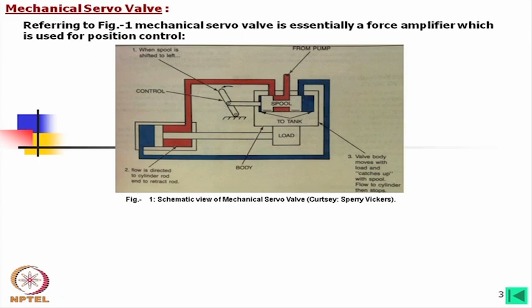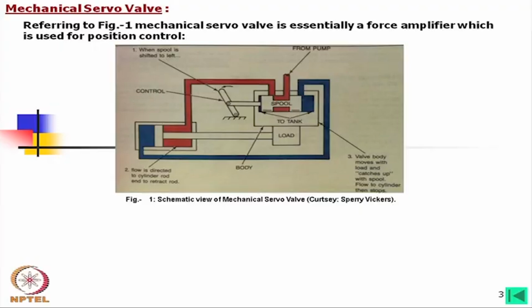For example, if you use a solenoid, a certain amount of constant input is there. So, due to this input, again this will open, again the valve will close, and this will go on. That will occur simultaneously and so smoothly that there will be no discrete motion of this body. So, this is basically what we should call a mechanical servo valve, a hydromechanical servo valve.